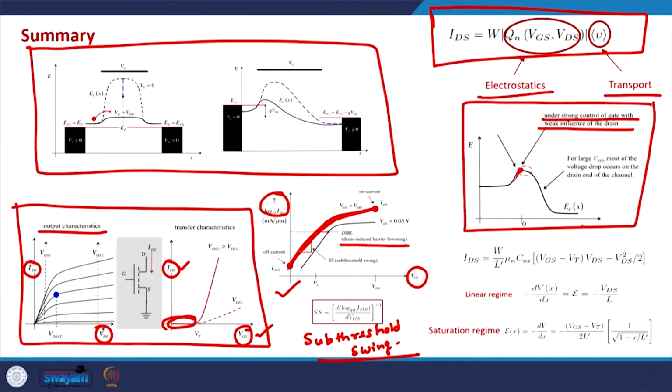When the gate voltage is below the threshold voltage, in that regime, this is the amount of the gate voltage that is required to change the current by a factor of 10. The unit of this is millivolt per decade, and there is a fundamental limit in MOSFETs on this quantity, and that is 60 millivolt per decade.